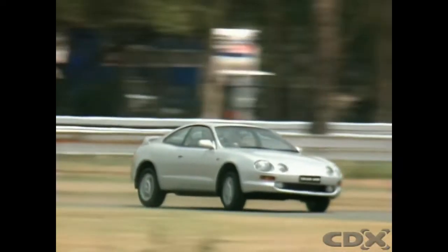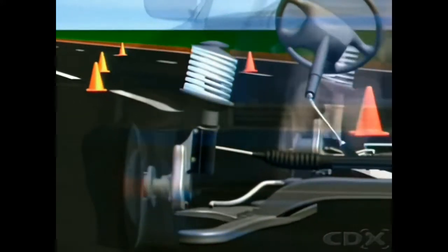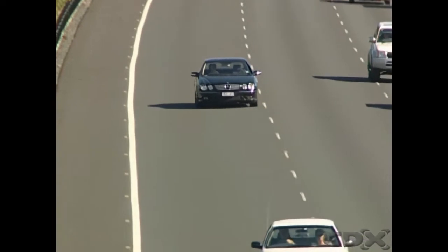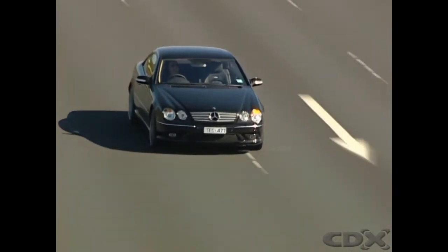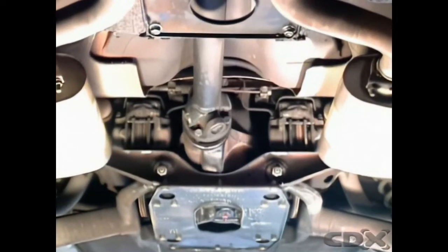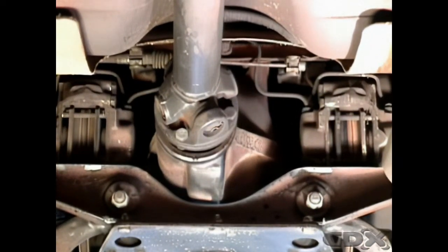The kind of independent suspension used on the rear of a vehicle depends in part on whether it is front-wheel drive or rear-wheel drive. If it is front-wheel drive, it may use a McPherson strut system at the rear, similar to the front suspension system. There is normally no steering on the rear wheels, so there is no need for the bearing in the upper mounting. On rear-wheel drive vehicles, the suspension arrangement has to allow for the external drive shafts to transfer the drive to the wheels. The final drive assembly is normally fixed to a crossmember, and since it must absorb the torque reaction, it must be secure.